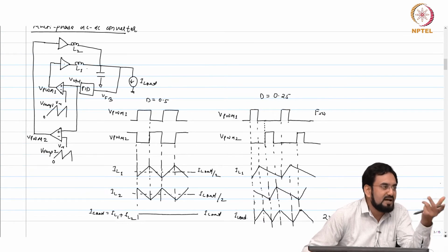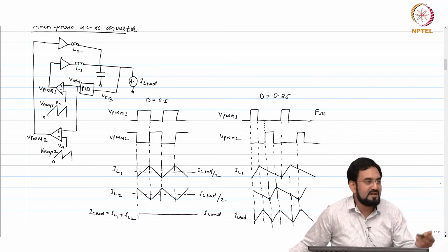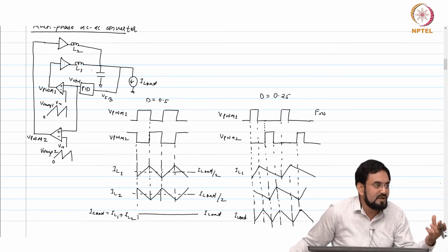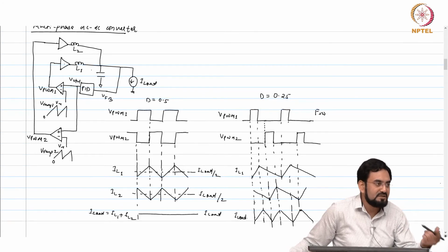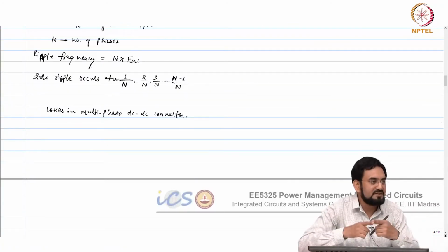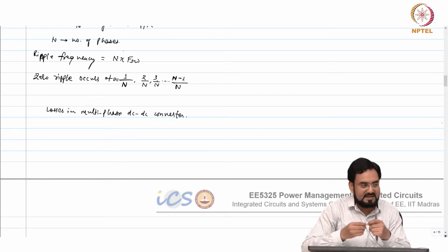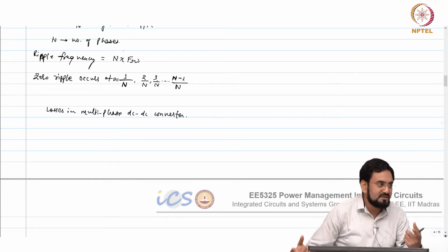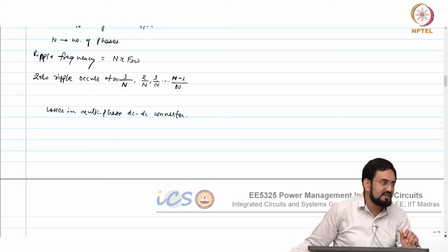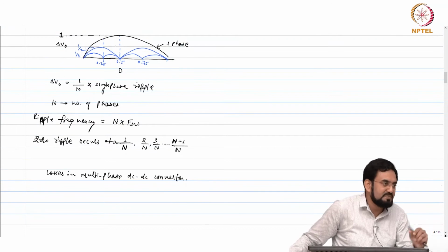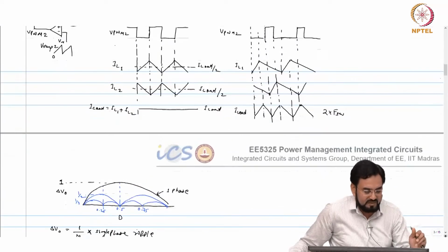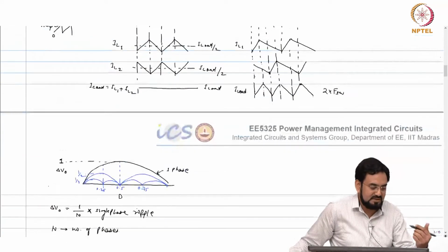So what we can do, we can use a higher DCR inductor that will have a smaller size. The lesser the DCR, the bigger the inductor is, because it requires a thicker coil. So low power inductors will be smaller in size compared to high power inductors. So still you can reduce the size of the inductor. Maybe after packaging it may not scale by 2x, not 50%, but 20-30% reduction you can still see by using lower power inductors here.